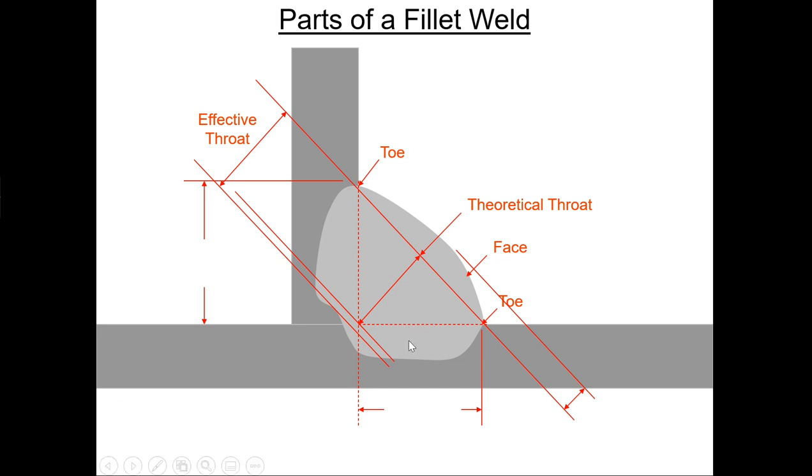There are many specifications that say we have to have a certain depth of penetration. And if you remember from the previous slides, if you've had a look at the previous presentations, I talked about how the base metal and the weld metal have to homogenize. The material itself borrows a few of the properties to try to keep the properties that give it strength as high as it can. So that's why depth of penetration is important to the process.